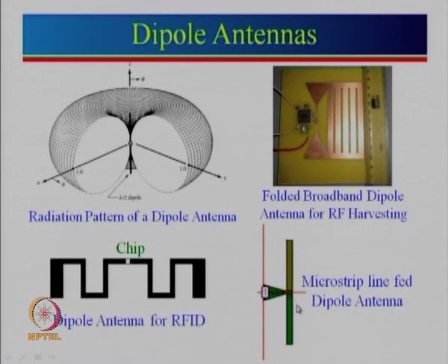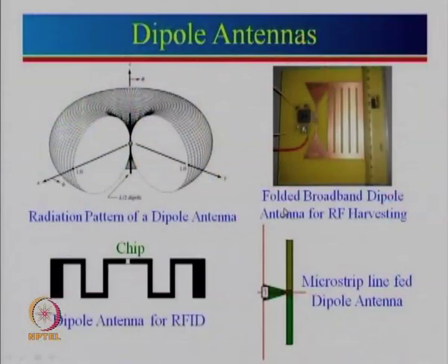to design a concept which is known as a BALUN, that is, balance to unbalance. Here we have tried to achieve balance to unbalance using a microstrip version, and that is a microstrip line fed dipole antenna. As we go along in the course, we will see how to design all these antennas.